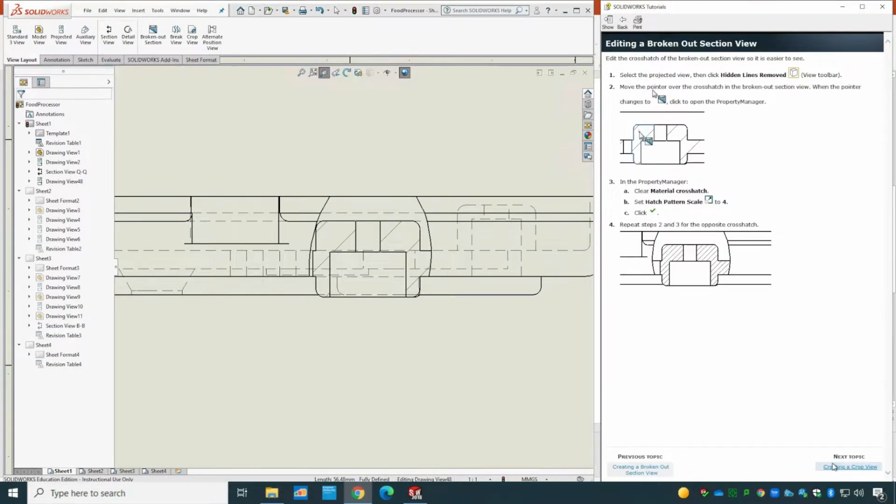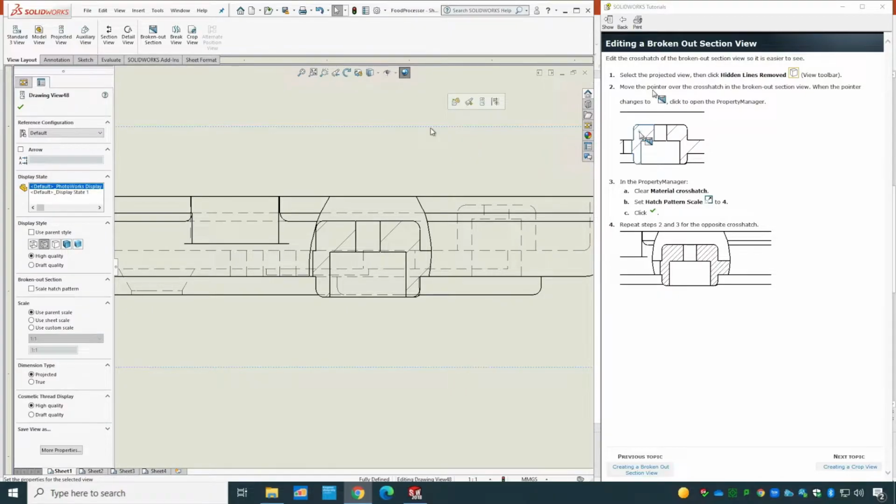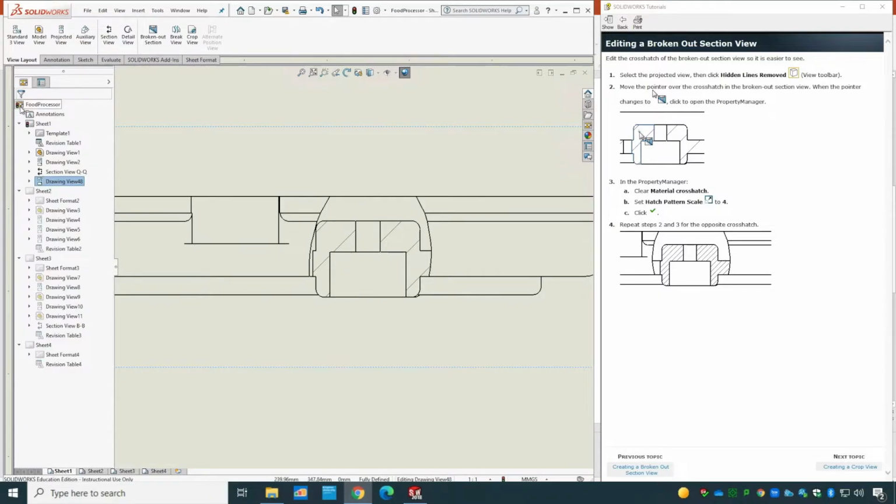So what I'm gonna do, I'm gonna get rid of all the hidden lines. So what do you need to do? Let me click on the scale to go out of it. So you need to activate this view, just clicking once on it, and make sure you change this one, hidden lines visible, to the normal one. Basically the hidden lines are removed, and click OK. I still see the section view that I created here.